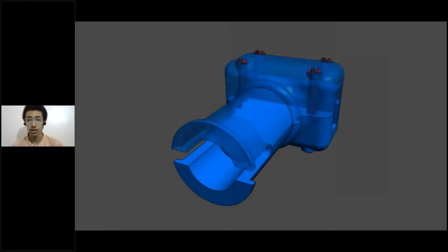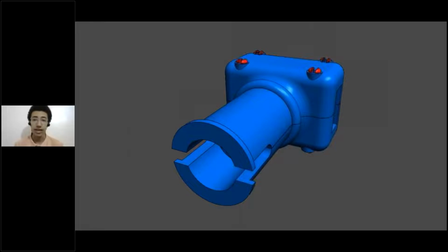You're going to see that the model is actually changing its transparency. So what I did is that I placed multiple key points in my animation, and at every key point, I changed the state of these components. So for example, I can change the color, I can change the display state, I can change the transparency. Anything is possible in SolidWorks animations while I'm using key points. Okay.